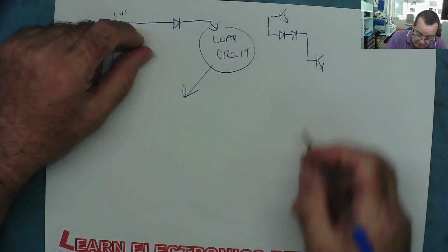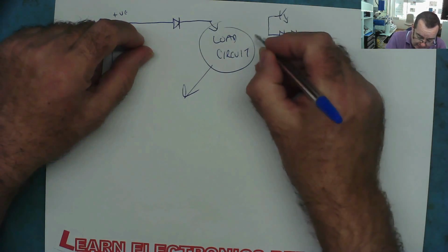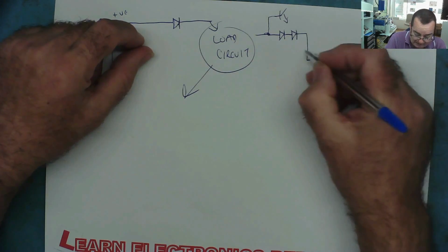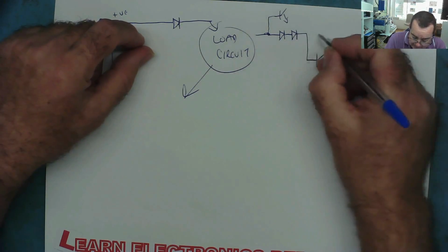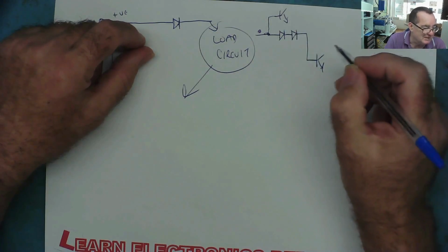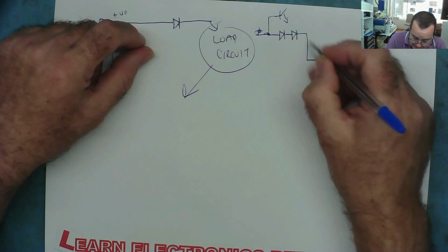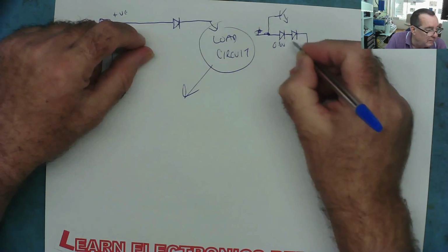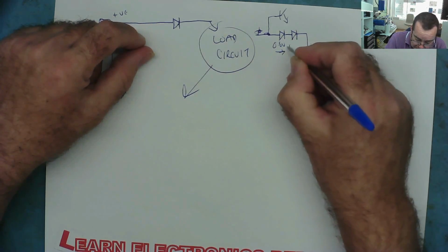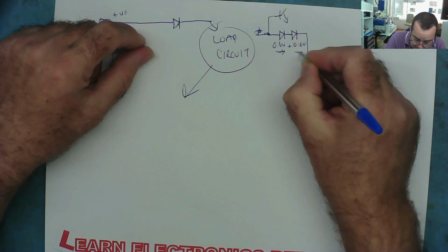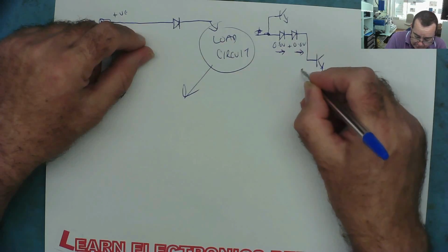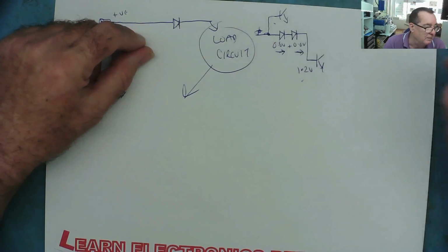So what happens now is that if you have a signal coming in here, the same signal comes, well, rectified, coming through here. If you have a positive voltage on here, the voltage on here will be 0.6 volts. That's the forward voltage drop. Plus another 0.6 volts, that's the forward voltage drop of the other diode. The voltage here will be 1.2 volts less than the voltage here.